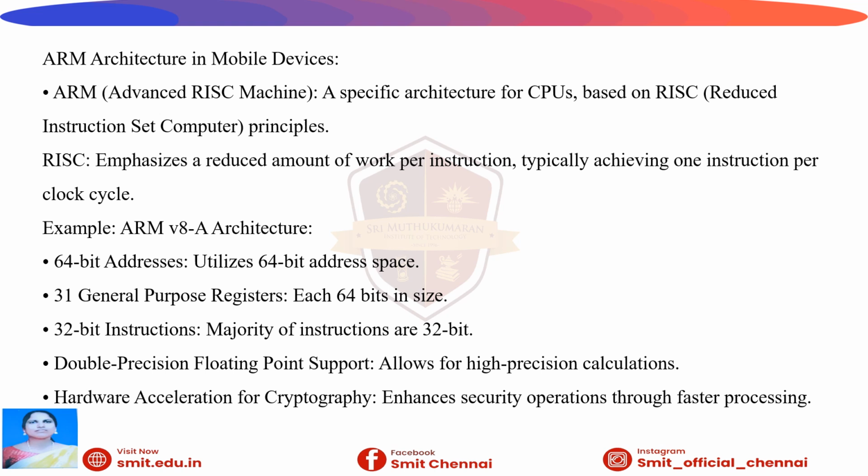Mobile phones require battery efficiency, so they utilize ARM RISC architecture, simplifying instructions down to simple commands executed quickly, so the device preserves battery. The ARMv8 architecture, 64-bit, utilizes 64-bit address spaces, 31 general purpose registers, 32-bit instructions, double precision floating point support, and hardware acceleration for cryptography. It plays an important role in enhancing security operations through faster processing. So that covers this slide on ARM architecture.